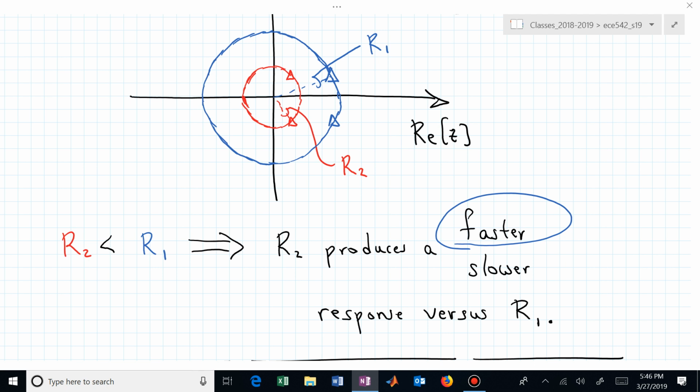Do you punt? Or just drop the ball? Or pass it to someone else and hope that they know how to work the problem? If there's nothing explicitly contained in the constraints, you may want to just say, let me make this as simple as possible. Let me make my poles real. If I don't have to worry about a percent overshoot or a peak time, maybe I just make my poles real, and I just need to make that real distance a value of r away from the origin, where that r now satisfies the settling time specification.